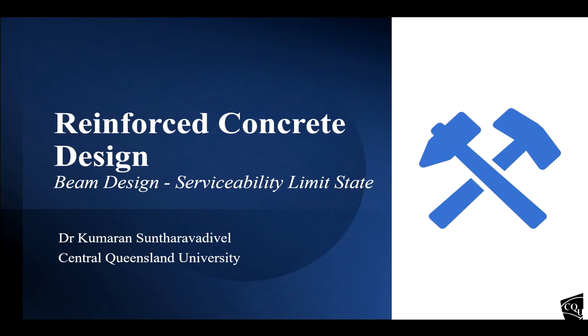Normally, we check the dimensions first, because we don't know them. If you are asked to design a beam, or a slab, first, as I discussed last week, we need to find out the dead loads and live loads. Live load can be obtained from Table 3.1. But dead load is basically the self-weight of the structure, or it can be any other permanent fixings.